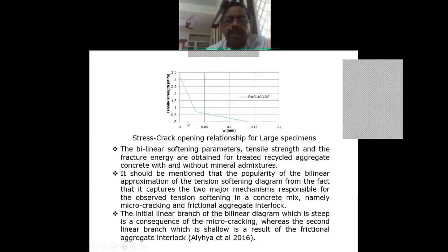That's why the energy is lost, reduced, and that way it is affecting your mechanical properties. By silica fume or fly ash or mineral admixtures, you can treat the micro pores and other things, and you can improve this microcracking a little, but not completely. You cannot avoid it, and that way a slight improvement is there in fracture energy and other things. But it definitely improves the mechanical strength.